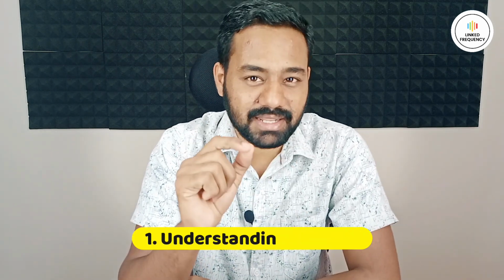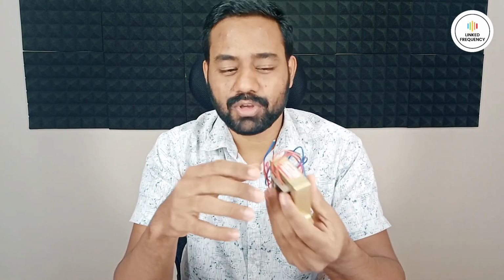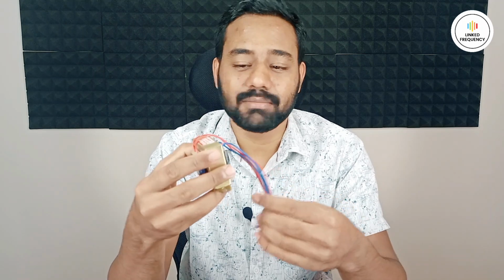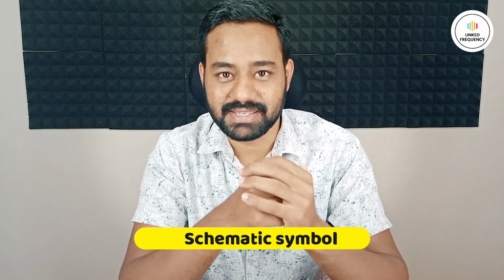First one is understanding the dimensions and schematic symbol representation of this particular transformer. An important note: we do not get the exact data sheet for these kinds of transformers available in the market, because most of them are locally made and do not have any standard manufacturing data sheet. If you find one, that is awesome. Use it and design based on that. If not, then you can purchase the transformer first, measure the dimensions, understand the schematic symbol, and create it according to that. Second step is creating a schematic symbol using EasyEDA, which includes IEEE standards and user interface as a priority.